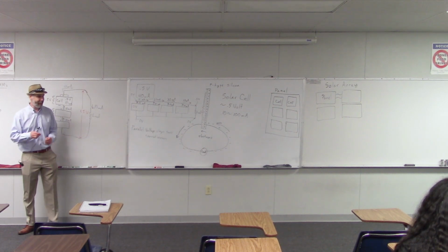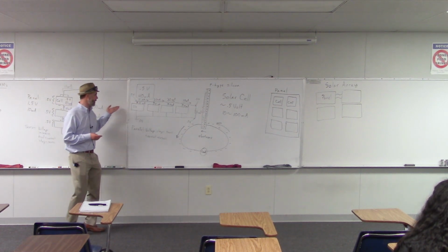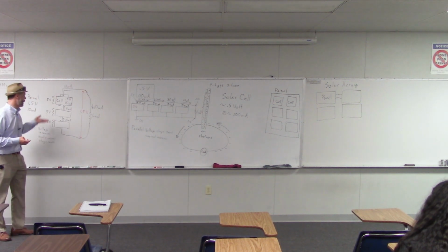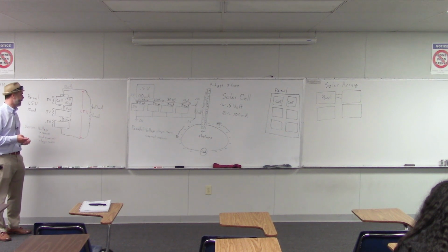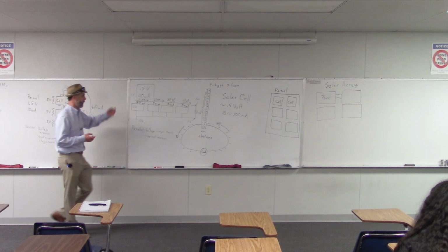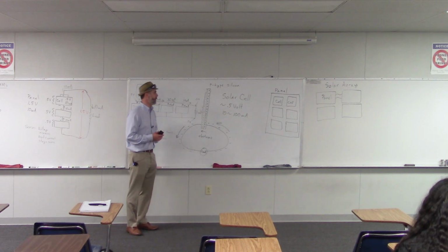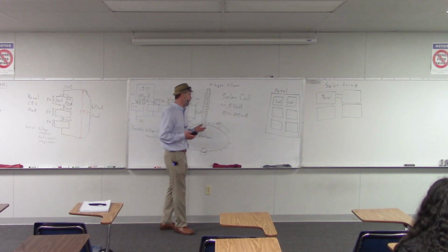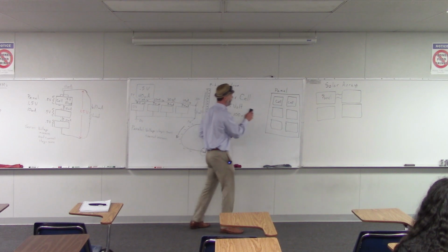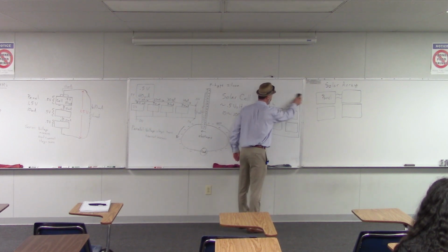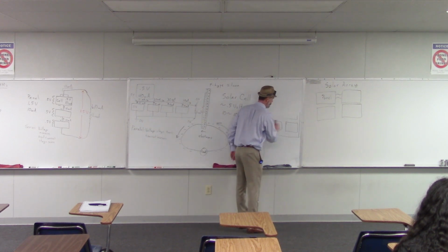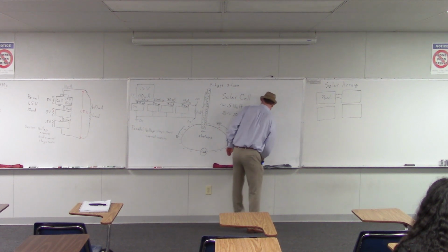Yeah, and they do it all using these same principles. They increase the voltage by putting the batteries together in series. They increase the current by putting them together in parallel. And in fact, sometimes you need more voltage and more current. So what do you think you could do if you need more voltage and more current? Series parallel, exactly.